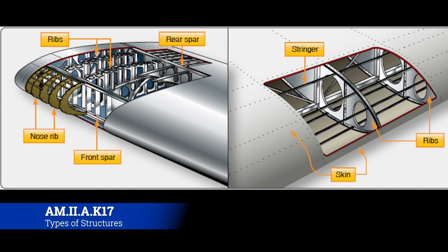So when you look at a plane and you see a bunch of rivets, what you're seeing are the rivets that are drilled through the skin and into the stringers or into the ribs to attach them. So the basic construction is the spar, then the ribs attached to the spar. The stringers then attach to the ribs to give it this structure. And at this point, the house is framed, and the last step is to attach the skin via rivets onto it.